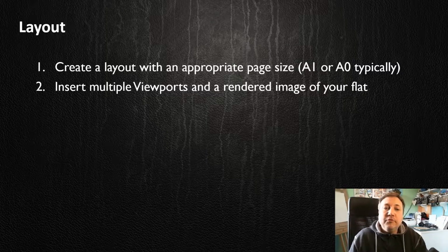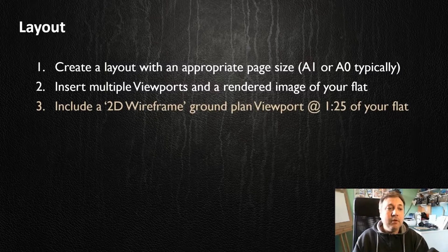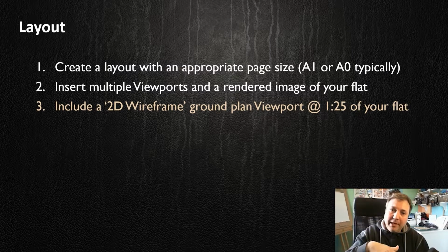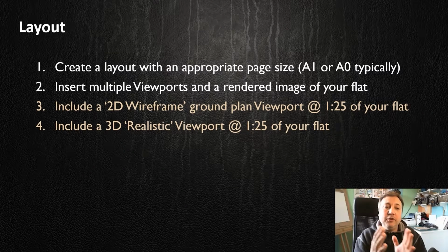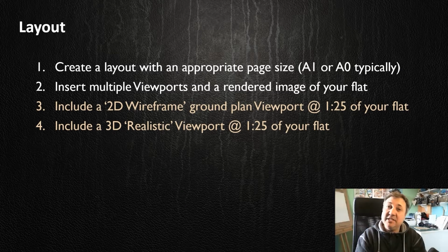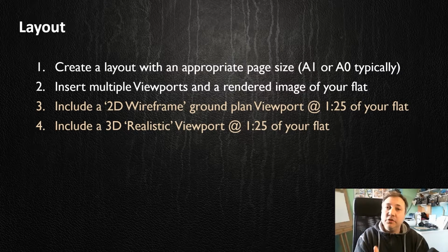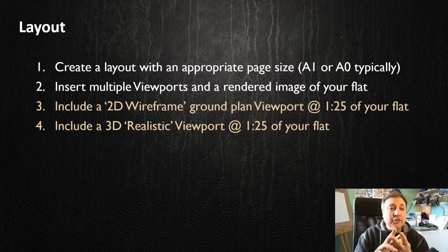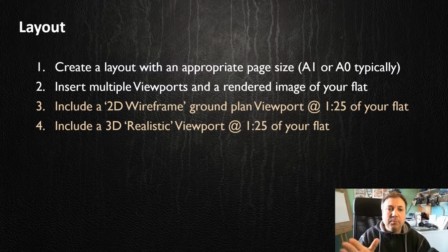And you're going to insert multiple viewports and your rendered image onto your page. And one of those viewports is going to be set up as a 2D wireframe, sort of ground plan, so a top view, in 1:25, showing your flat with the dimensions on. And you're also going to include a viewport that's got a 3D set to realistic view at 1:25 as well. And anything else that you feel appropriate. So they're the two viewports that we need, but you may, of course, choose to show it from the side or from the top as well to fill up your page.